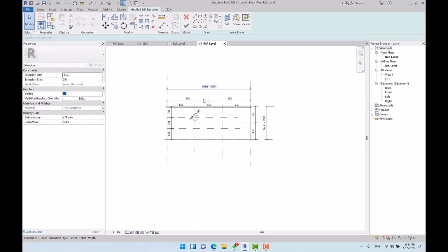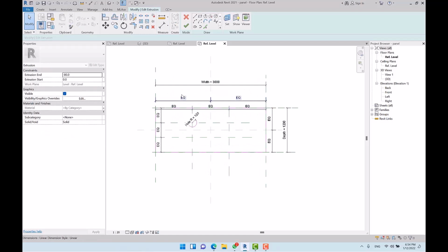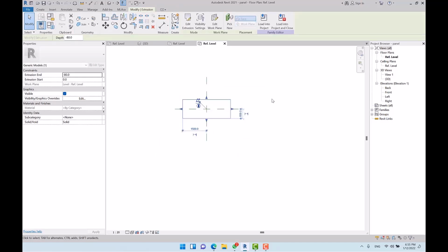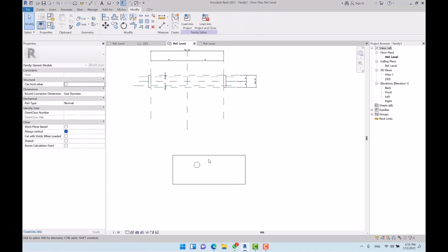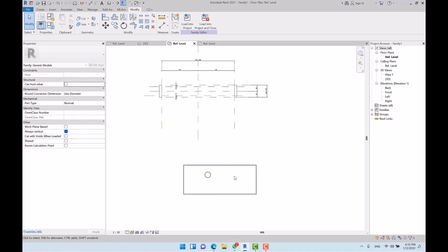Check this out, the exact places that we got reference plane, aligning is available, so there are some limitations in aligning. So the places in which we got reference planes, you can align other objects to the reference planes. So if you wanted to align your object to the another object, you should use reference planes as a medium here between these 2 objects to be able to align these 2 objects with each other.